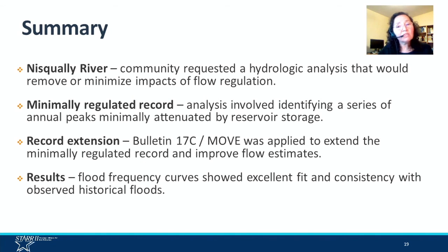So to recap what was done, due to stakeholders' request, the hydrologic analysis to update Nisqually River effective flows needed to exclude or minimize the impacts of flow regulation due to Alder Lake Reservoir. The analysis applied involved identifying minimally regulated events, which are annual events that were not much affected by reservoir storage. We developed a new record with these events, a subset of the original record at each regulated gauge.